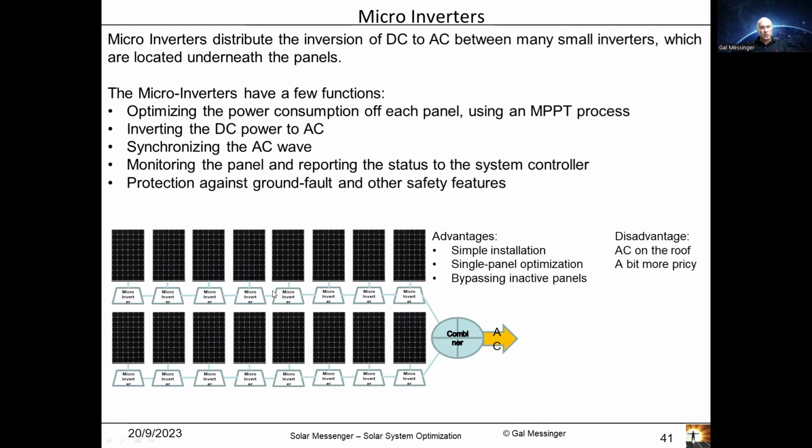There are a lot of advantages to this because if one of them fails, you still get a lot of production. They're optimizing the power from the solar panels, called MPPT. They follow the current and voltage to optimize what you produce. It also has some protections and monitoring capabilities. So if one solar panel is not producing enough or fails, you would notice. And if there is a short, or short to ground called a ground fault, the optimizer is going to shut down that panel.